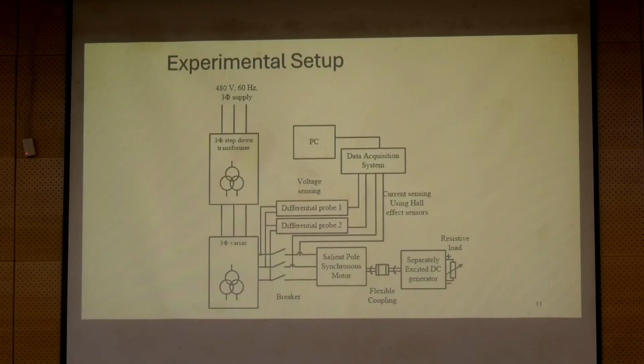Okay? And then I measured. The stator of this machine is Y connected with a neutral point not brought out. And therefore, I know that in a system like that, the sum of instantaneous values of currents and voltages should be equal to 0.